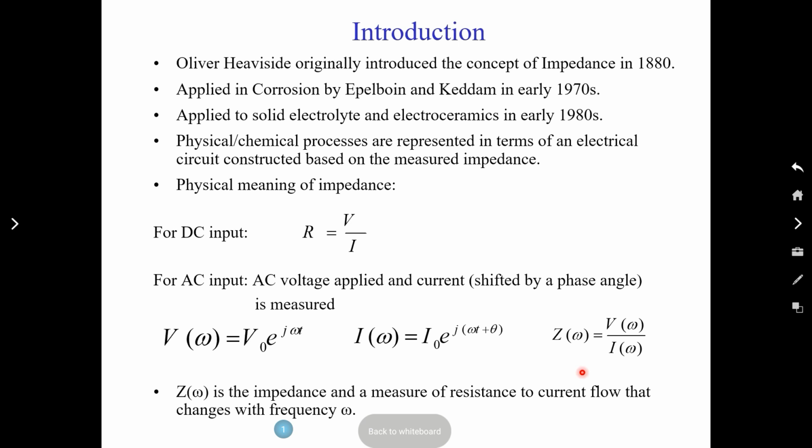In the impedance analyzer, you put two contacts on each side and apply voltage as a function of frequency. You can start with, let's say, the lower end, microhertz. By the way, the larger the frequency range is, the better you will be able to capture all the processes, because all these processes have different relaxations.